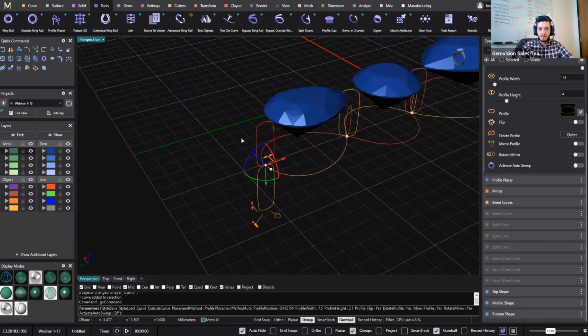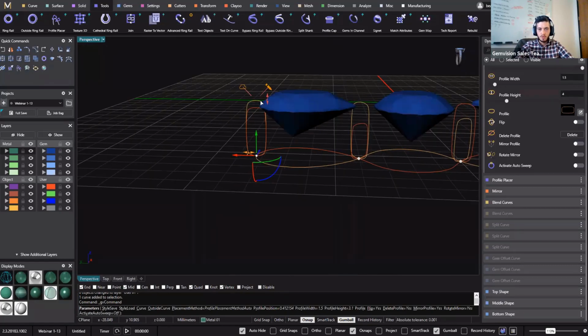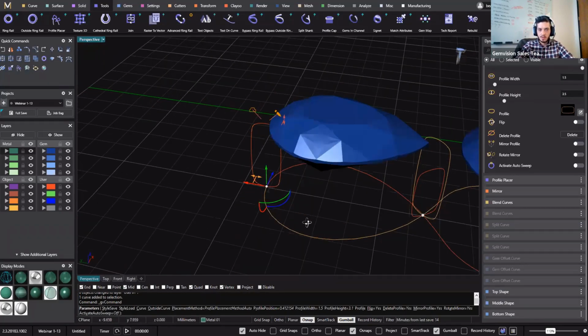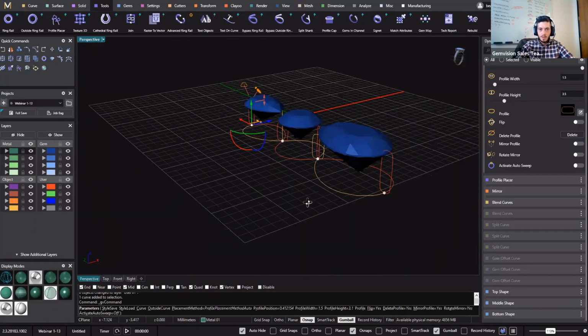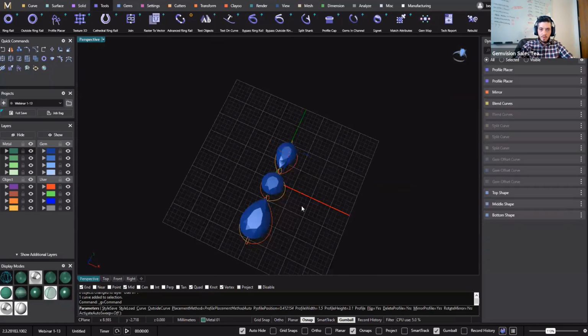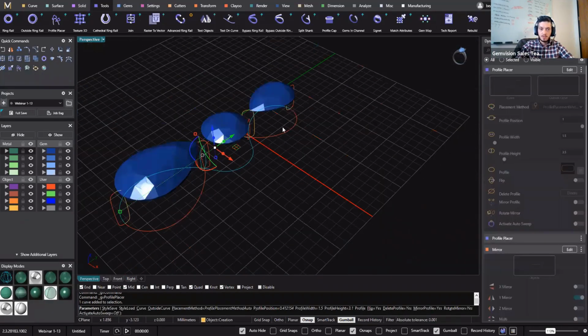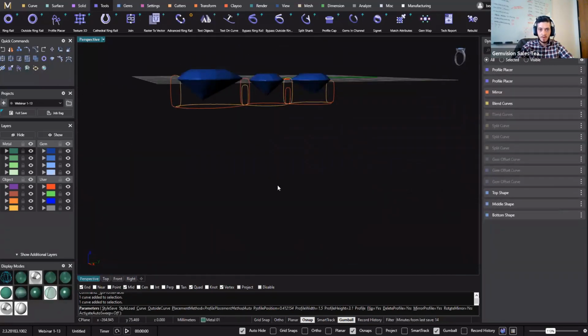So let's left click. Let's take blue arc and move it, and then we're going to match it like this. All right, so when I right click, I should have yellow profiles for my yellow curve, and I should have red profiles for my red curve, right?